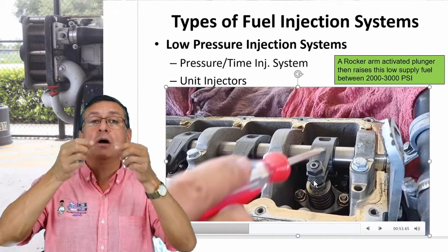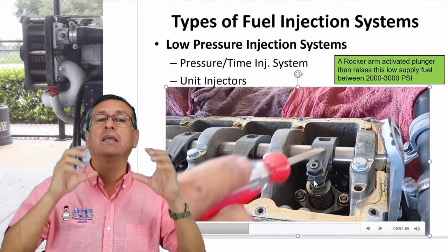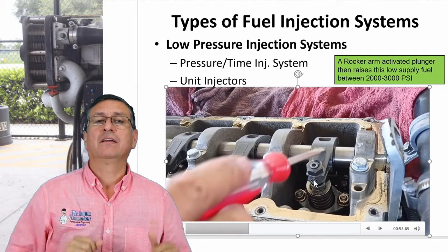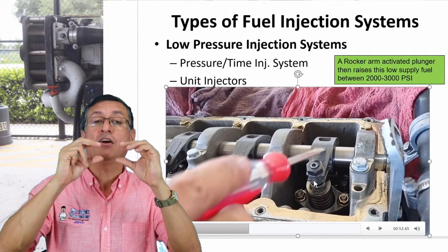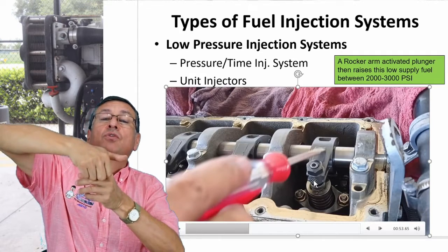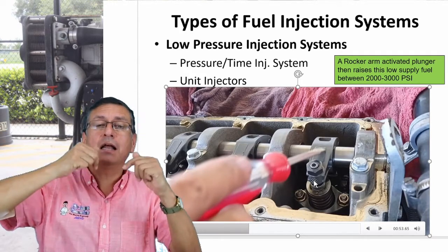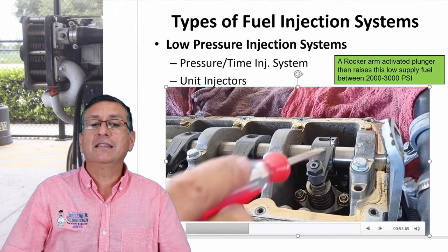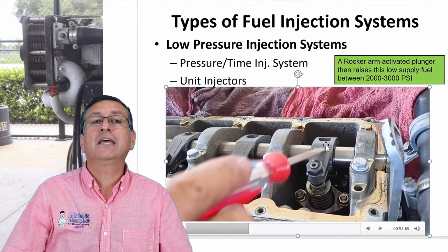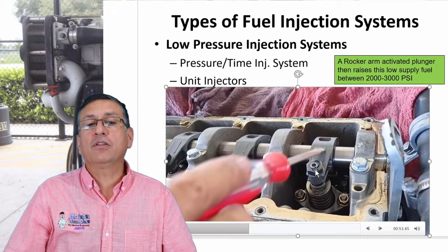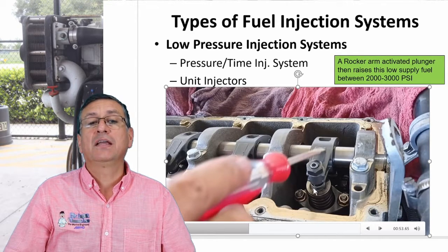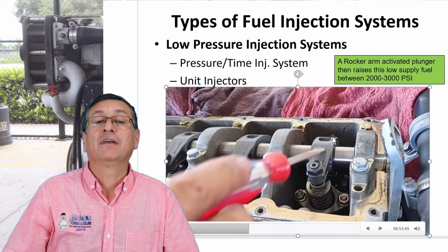The injector on top looks similar to the spring of a valve, but it is not. This is the spring of the injector, and it is used to compress the internal spring of the injector. And this rocker arm is dedicated to compress the injector. At the other end of this rocker arm is the camshaft.